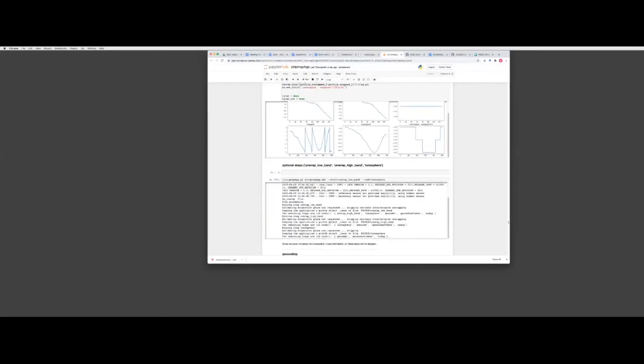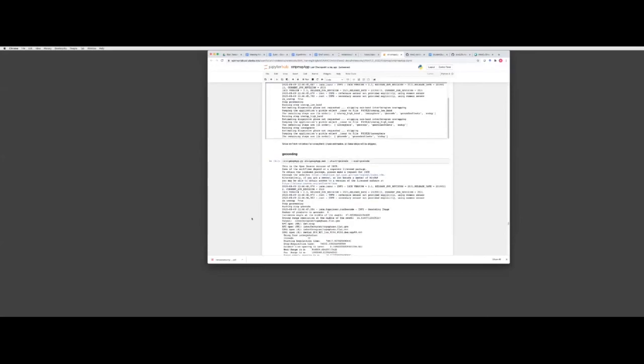The next step is Ionosphere, which is optional, and we will get back to it on Wednesday. But go ahead and run the last step, which is geocoding for today. Clearly, this step is going to geocode the interferograms. So far, whatever you have seen was in the radar coordinate system, in the range Doppler or range azimuth coordinate system.